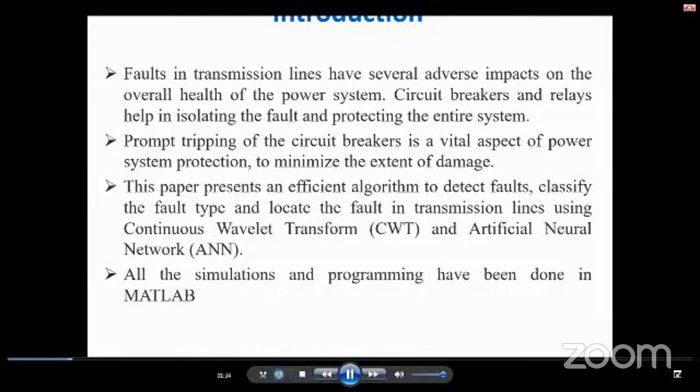The purpose of the protection system is to isolate the faulty section from the healthy one because the fault currents may damage the electrical equipment. Distance relaying is a major kind of protection system, and it also works as a very good backup protection. So it is a very good protection system for the transmission line and the entire power system network. The objective of this paper is to demonstrate the application and advantage of the technique of signal processing in modeling of a transmission line relaying scheme.